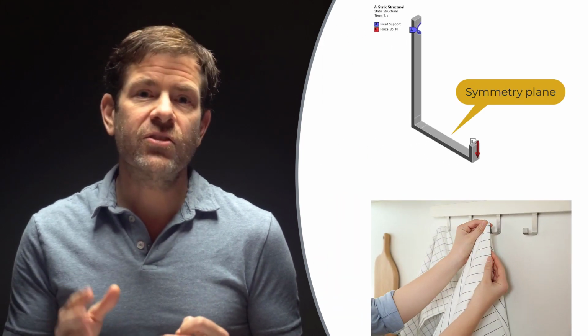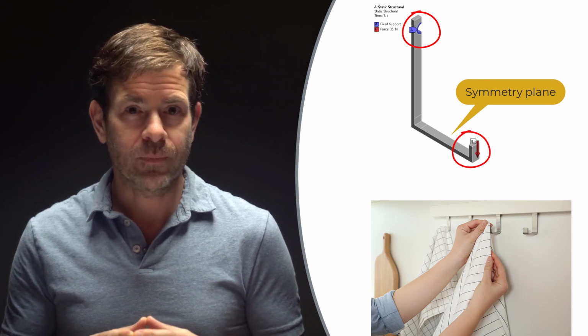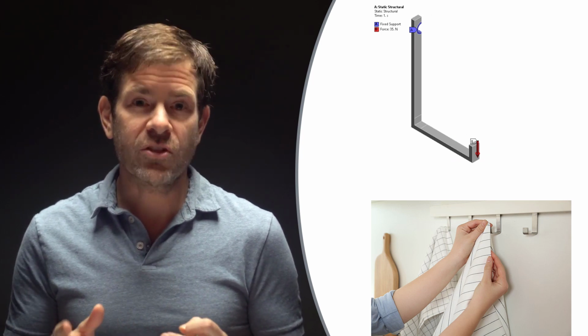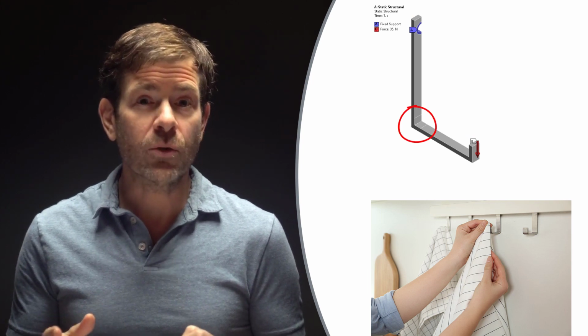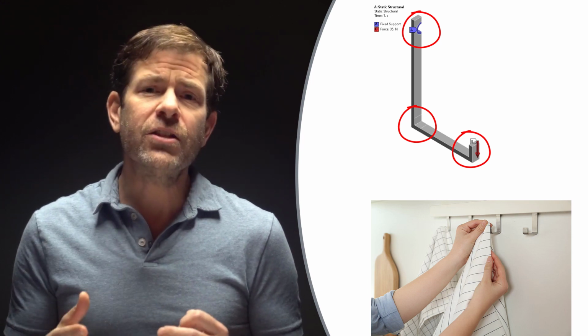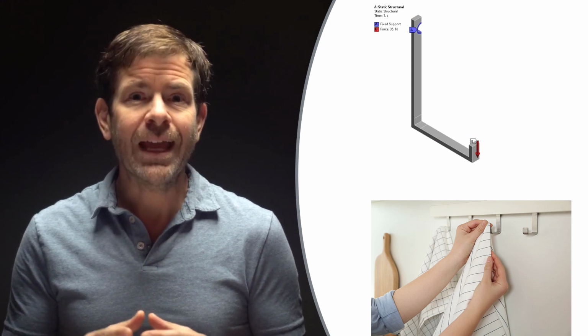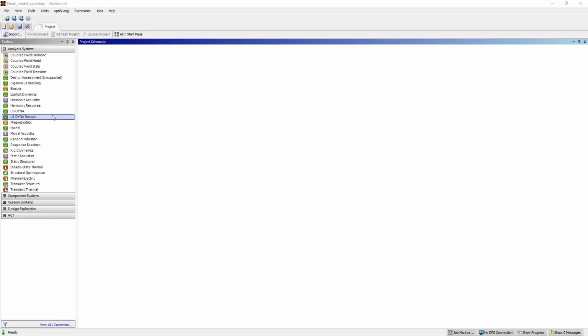Now let's see how to resolve the artificially high stress in a walkthrough example in Ansys Mechanical. The example shows a half-symmetry steel hook that's attached to the wall by a screw and exposed to the force at the hook's tip application. This example will address problems such as re-entrant corners, point loads, and constraints that can cause artificially high stresses in the model. In addition, we'll show the ways to improve the model by better preparing the geometry and applying proper loads and boundary conditions. Let's get started. Go to the project page and insert Static Structural System.